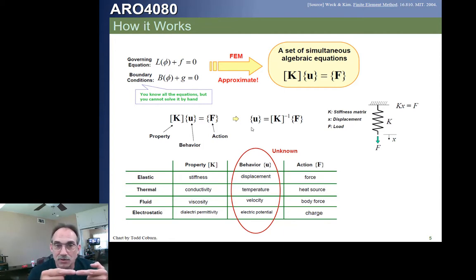Now, if you have an axial spring, that's pretty straightforward. If you have a rod, it's going to work the same way. If you know what the stiffness is, you can just multiply by the displacement. That will give you the force, or solve that in another manner. If you have a plate, you're going to have stiffness in the extensional direction and the shear direction and in the rotational directions, maybe in 3 directions on each one. Okay? So basically the idea behind this finite element method, or many finite element methods, all it involves is idealizing your structure so the computer software can figure out what elements you're using and how they're tied together.